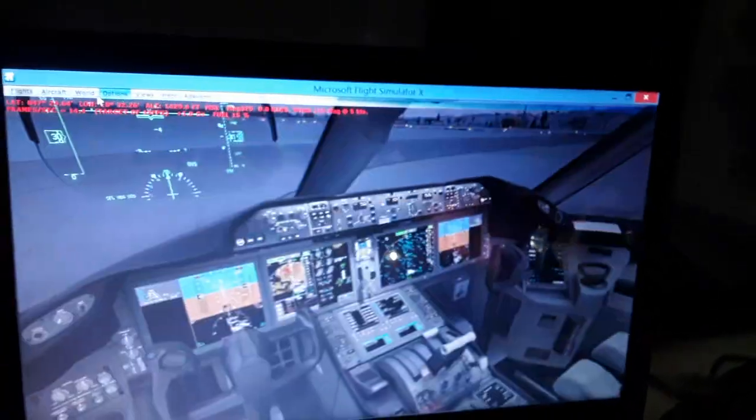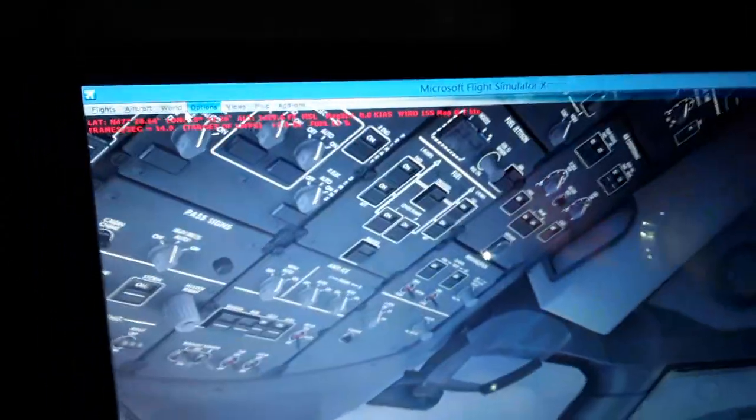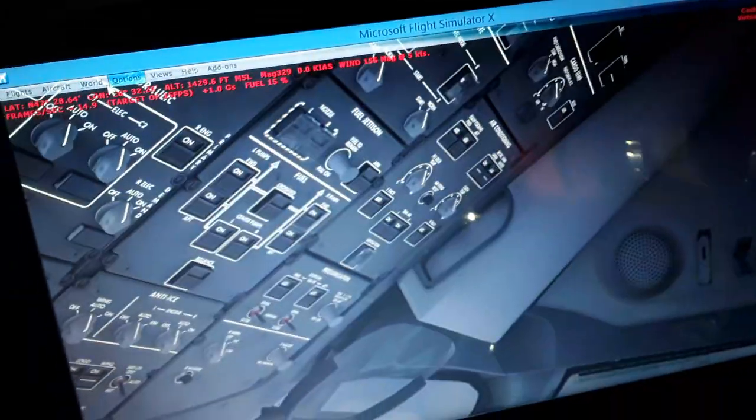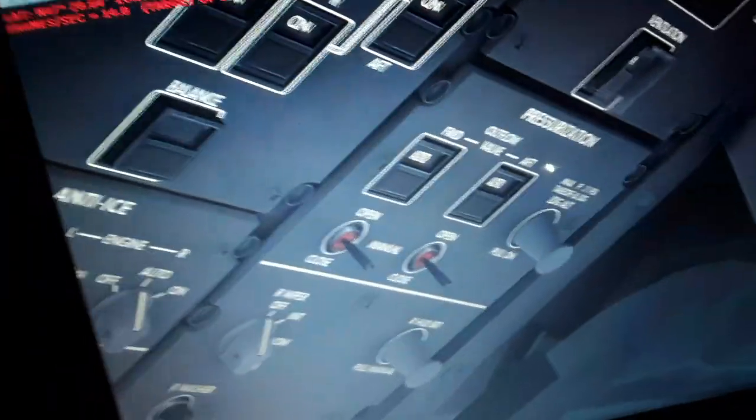So it can supply other systems that need pressurized air like the cabin pressurization system as we climb and the aircraft will pressurize. Also we need the oxygen regulation in the cockpit and the cabin, and also air conditioning ventilation, wing and engine anti-ice, and also the hydraulic fluid tanks are pressurized from the engine's pressurization outflow valves. So I'll show you the displays of that. Also you can see here the hydraulic pumps here that are pressurized. We have the primary demand hydraulic pumps, and also the tanks are pressurized with air from the engine.